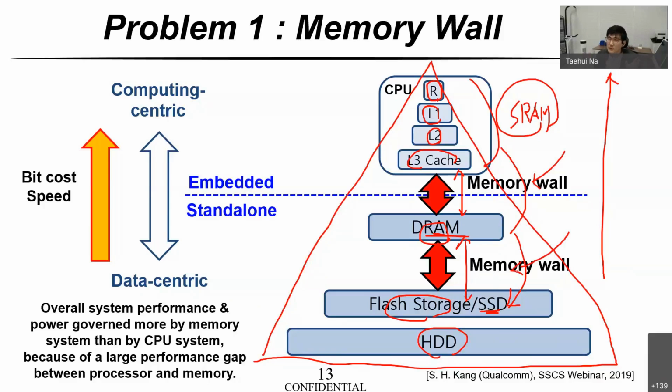So a fundamental way to overcome this memory wall problem is to modify the memory system by using a unified memory that has high performance and high speed like SRAM, decent memory density like DRAM, and non-volatility like flash. If this kind of new memory exists, the computing data don't need to be transferred from the SRAM to the flash storage. One candidate for this kind of new memory is STT-MRAM. So I will discuss that. That's why I am addressing this issue.